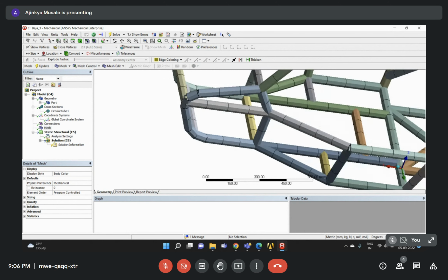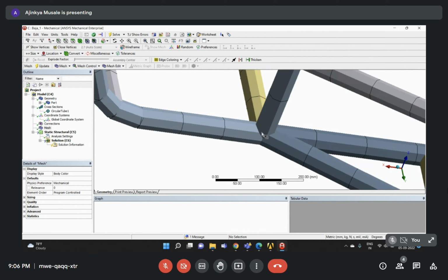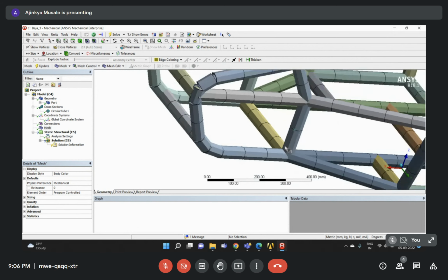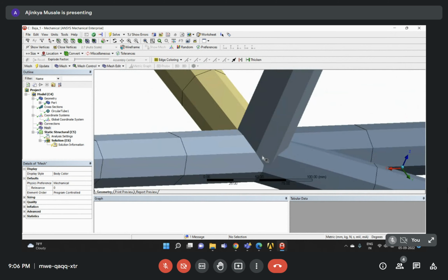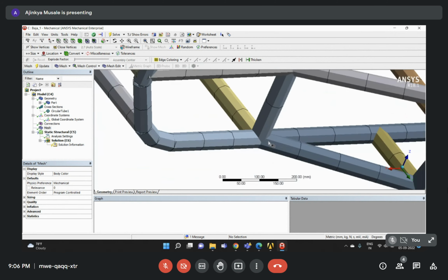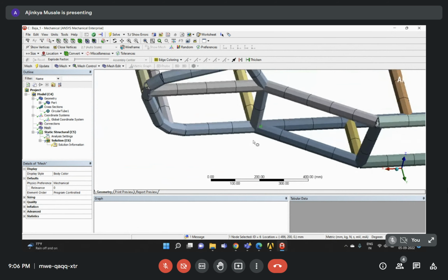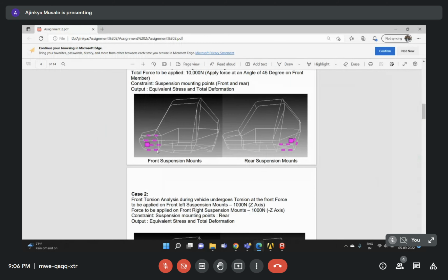Now I just hit node selection. So I go over here. Here basically I will have only one node because I have shared the topology. I simply check where I'm having that node, or I can just have box selection and do it like this. So yes, this node has been selected. Now I'll hit Control and select one more over here. Let's see which nodes I'm having: one, two, three, four, and the same nodes on the top member also.